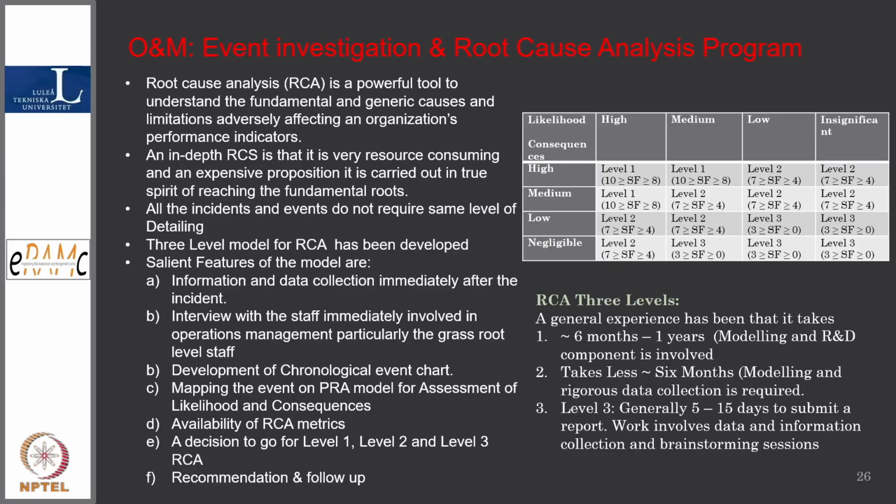And then O&M event is so root cause investigation and root cause analysis. Small incidents, they keep happening in the plant. So it is better to pay the attention, and these things should be nipped in the bud actually, because if we do not take control of those things, they get aggravated. So incidents should be seen seriously, and for that, if required, root cause analysis is not performed for all the incidents, but for low consequence events, they should not repeat, and there should not be any generic factor in that event.